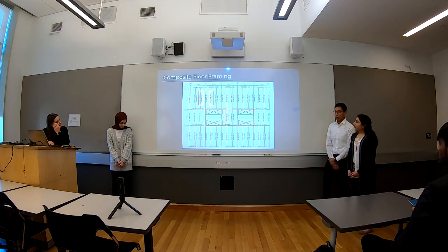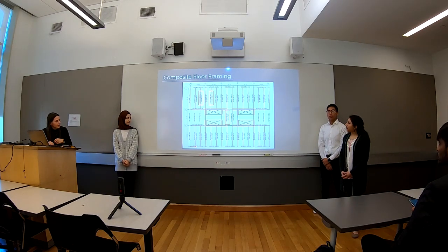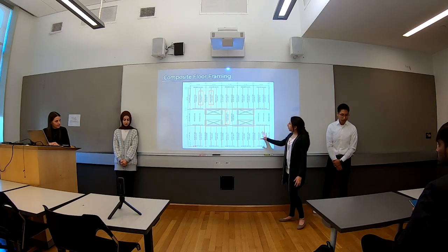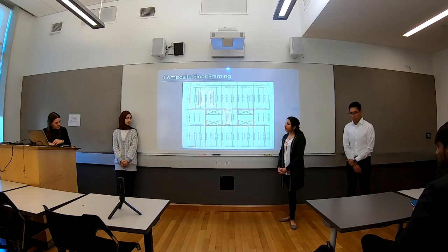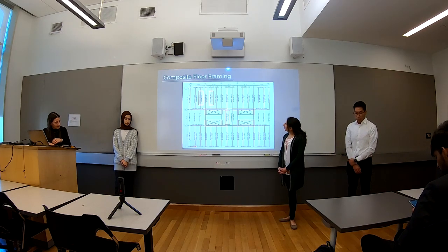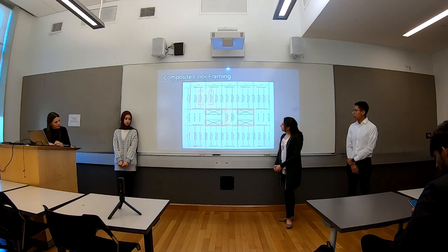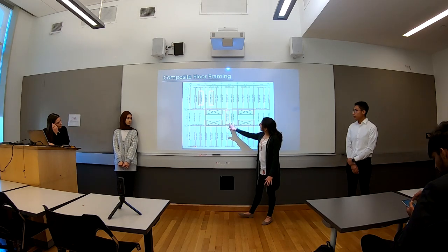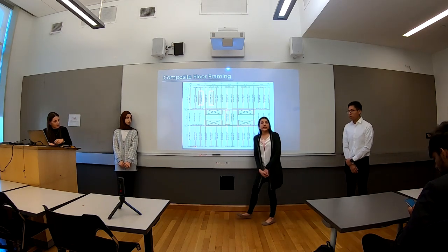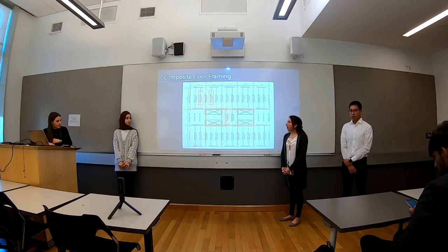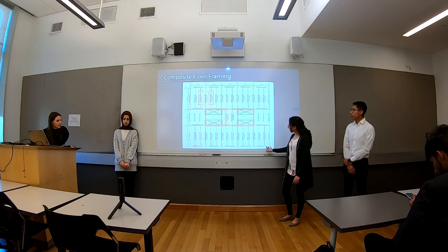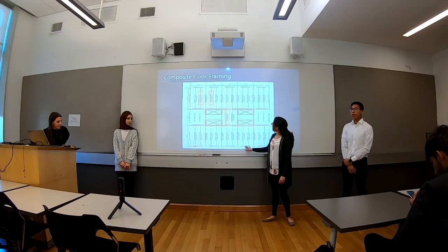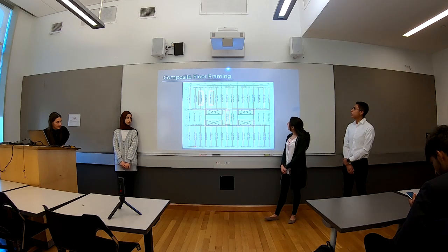Here we have a typical layout of our floor plan with composite beam and girders that we designed for. The interior beams are mainly designed with a typical I-beam section width of W18 by 40. There are a few exceptions being W16 by 26 and W21 by 44. That is because it was the most feasible option for our ceiling heights and other requirements. Then we have our girders, which are typically W24 by 55 as well as W21 by 44.